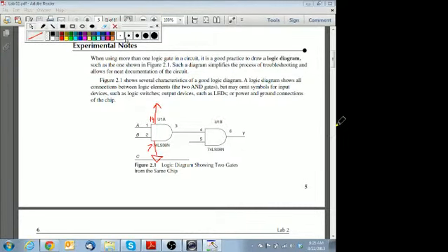That goes counterclockwise too, A and B, and then the top two would be C and D. It usually follows the pin numbers. So whatever package has the lowest pin numbers would be A. Whatever package has the next sequence of numbers would be B. That's typically the way.